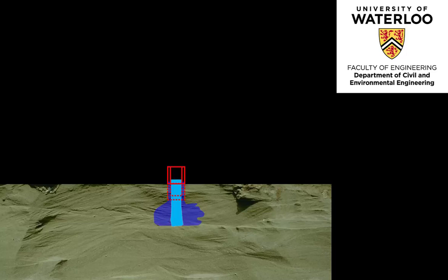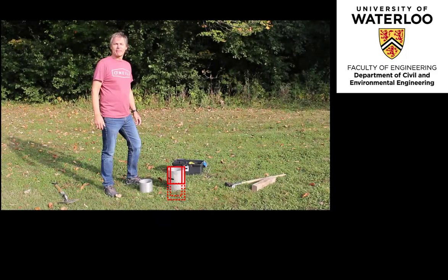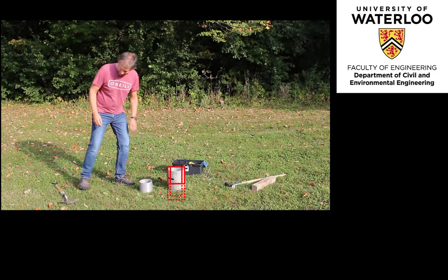The employment of the double ring infiltrometer technique allows the water that is displaced from between the inner and outer cylinders to compensate for the transverse dispersion within the porous media, while the volume of water displaced within the inner ring allows for percolation of the wetting front through the soil profile more closely to emulate the vertical one-dimensional flow field. Here we will begin the procedure by removing the sod from around the cylinder where the test will be